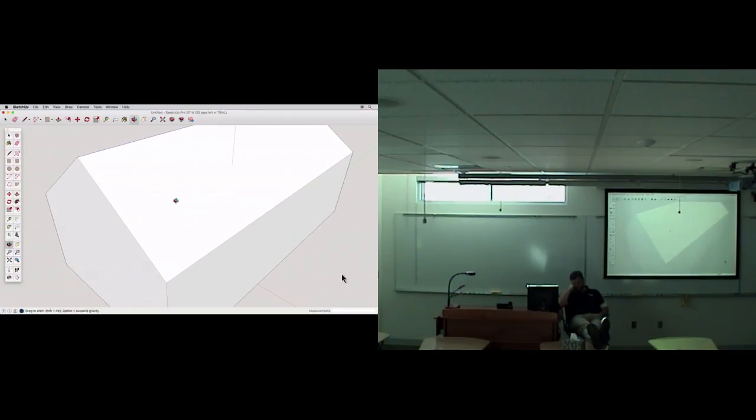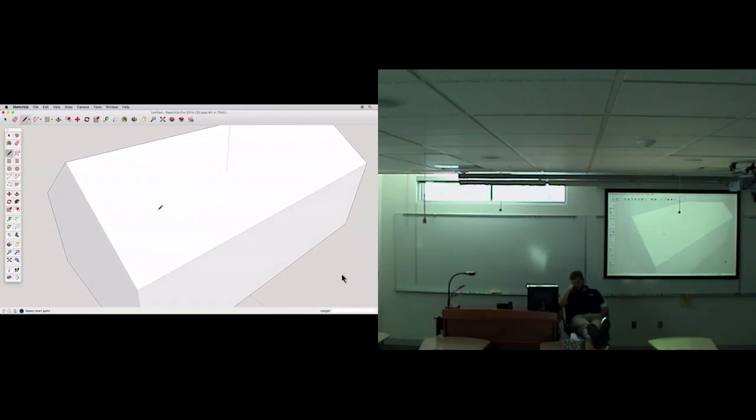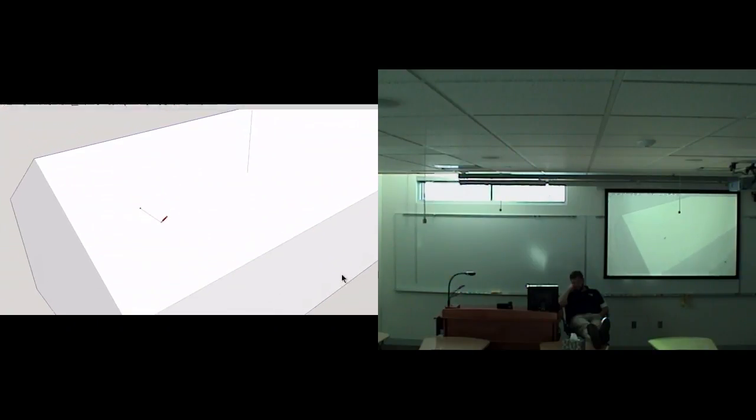Navigate for a better view of the roof surface. Now, use the Line tool and click once on an upper part of the roof to start drawing a line. As you move the line around, watch how it will snap to a red direction, a green direction, and a blue direction. Try drawing a line in each direction and orbiting.